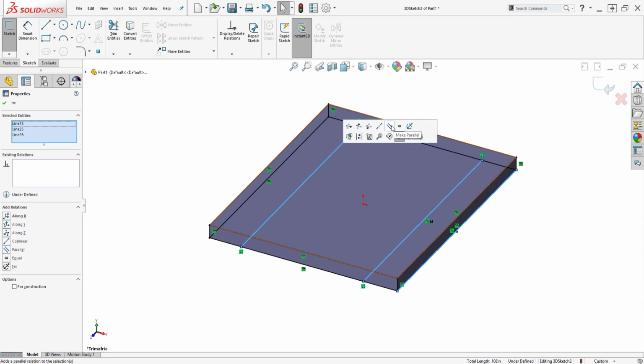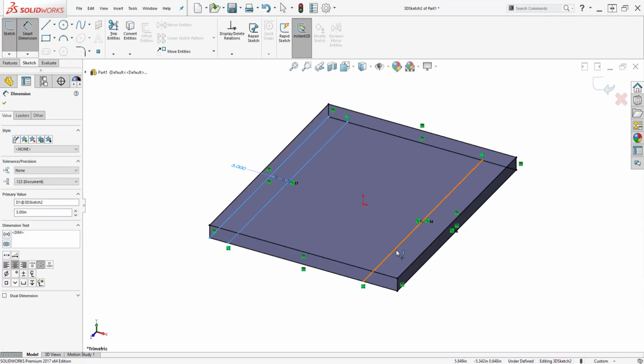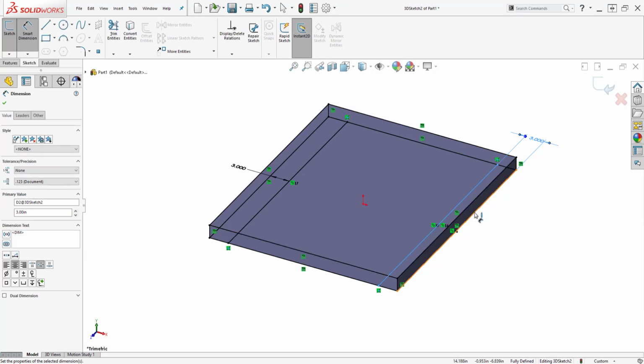For most wheels, we set our frame rails back from the perimeter about 3 inches. Since you will have already selected the wheels that you're going to use, you're going to know if this is sufficient or not, or if you have other reasons to shrink your robot, you can do this now.